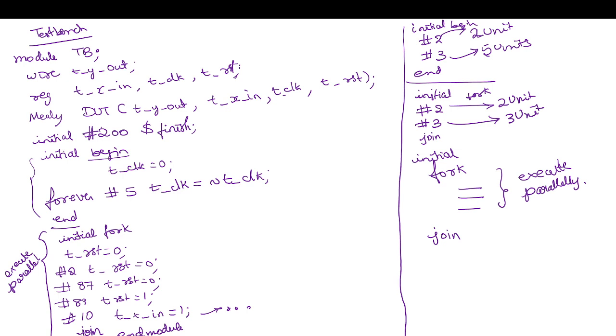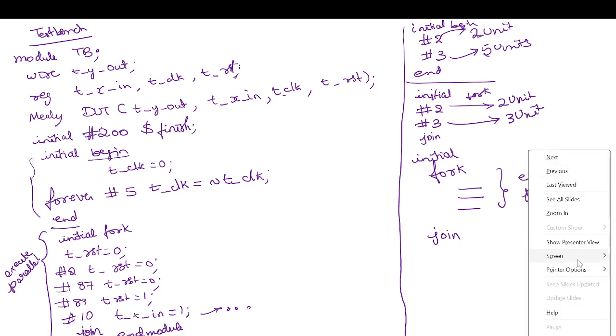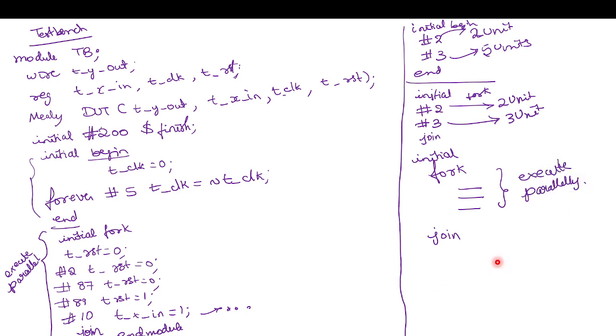In the test bench, these are my output port, and the inputs are the input, clock and the reset. Now I am passing it positionally. First it was the output followed by the input and then clock and reset. If I change the position, I will be using the dot operator, with the variable name in the test bench being different.